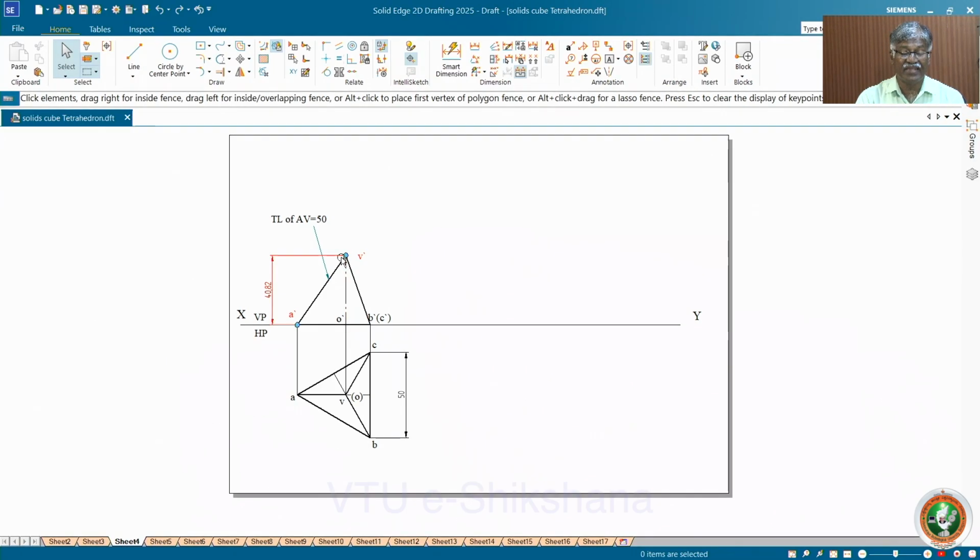So here, after getting this top view and front view, fixing the height using side equal to radius, with A dash as center, get V on the vertical projector of V. Then you have to consider this surface. Normally we consider this or this one. Okay, so I have done both here. Now first let me consider this. So usually we consider this as the base, then we take the slant face as the reference and give inclination to it. How to give this inclination?